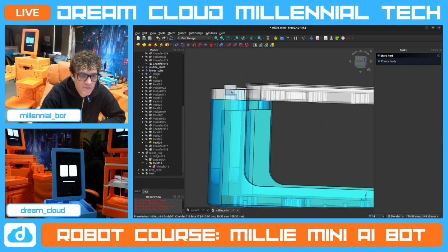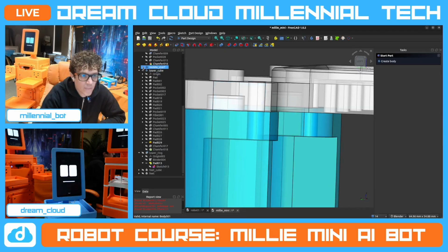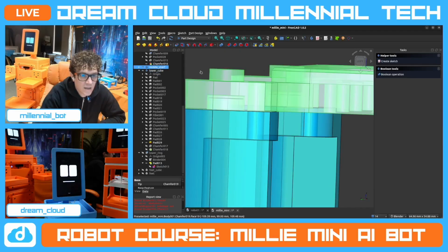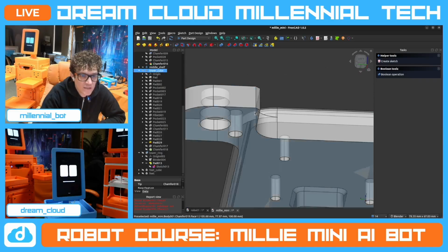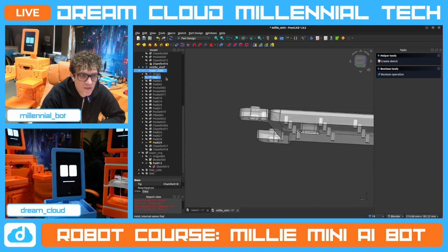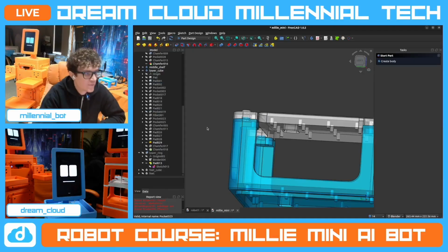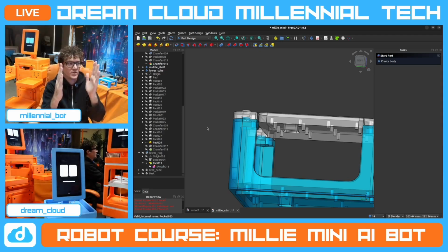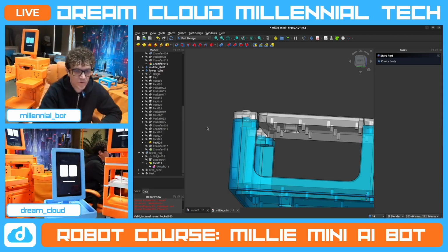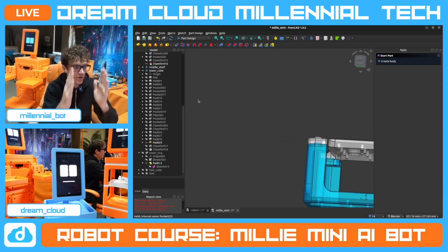These right here go inside that section, which is just hollowed out on the next piece up. So those stabilize it, because you'll find that if you 3D print things, they tend to bow out as you print them up. They go out this way, and that's just because that's how the printer is functioning. Not everything is perfectly aligned.